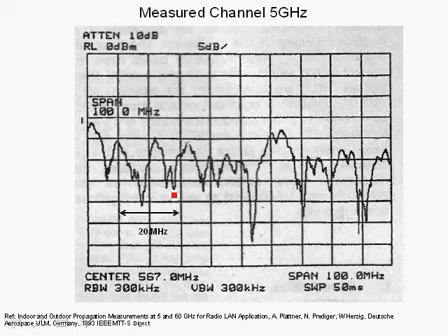So we see that multipath fading is a problem in communications, and we have to come up with modulation schemes in order to combat multipath fading channel issues. OFDM is one modulation technique which addresses this problem. We will discuss it in detail and show how you use multiple carriers that are orthogonal to each other and spaced very closely in order to transmit the signals in very narrow bands, so that within each narrow band, you have flat fading instead of the case of a wide band where you have frequency selective fading.